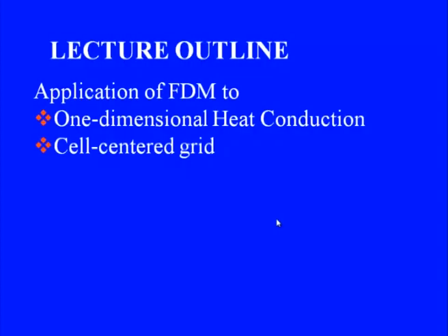Now today I would introduce yet another concept that is related to the choice of our grid, which we call cell-centered grid, and the cell-centered grid is specifically of great importance in the context of Navier-Stokes solutions, wherein cell-centered grids are primarily used.